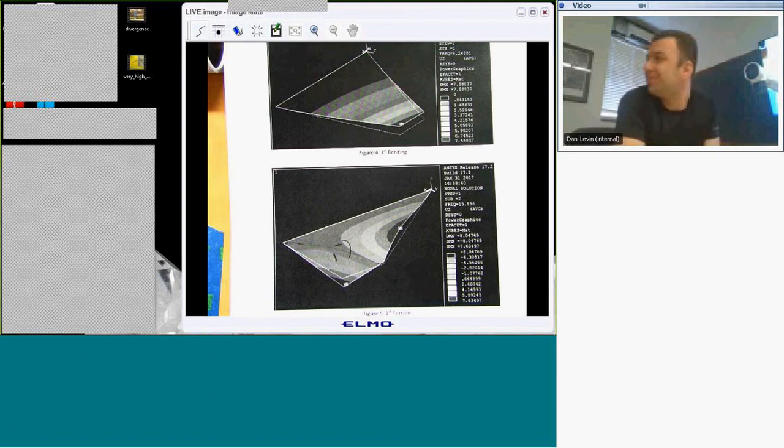But sometimes, well, you'll see in the test, I don't think we're going to go that far, but if you ran the airspeed high enough, the oscillations get large enough that some portion of the wing would have a stress level exceeding the yield stress of the material, and you would plastically deform it. And once you plastically deform it, it's not usable again.